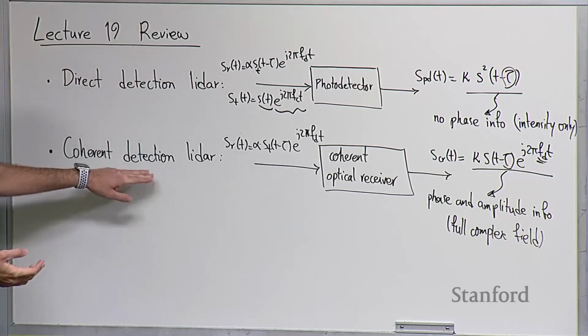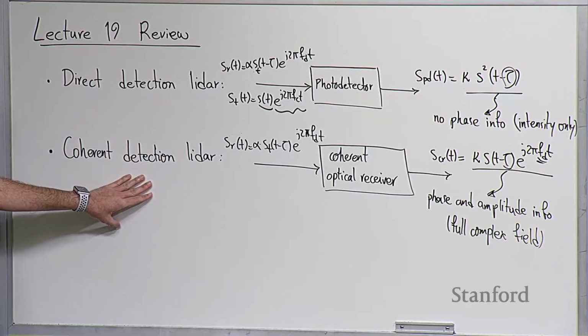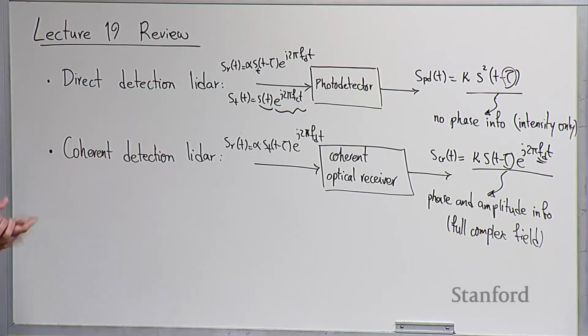Then we also said that the waveforms of coherent LiDARs are similar to what we looked at for radar. You can do frequency modulation, so you can have FMCW coherent LiDAR, which sends linear frequency chirps as waveforms, or you can have phase modulated systems that use ranging codes, like PMCW radar, CTFM sonar, or GPS as well.